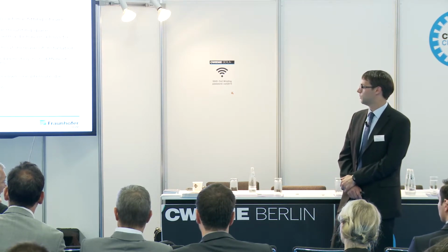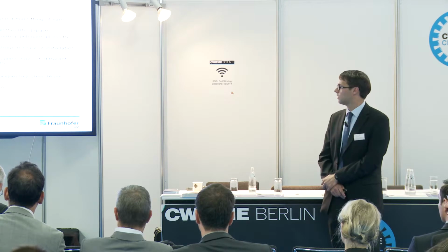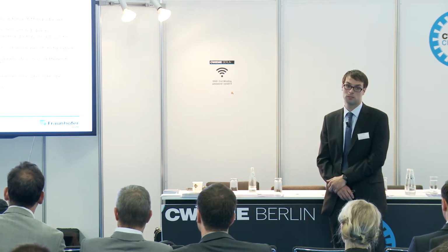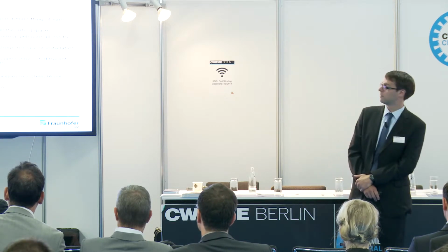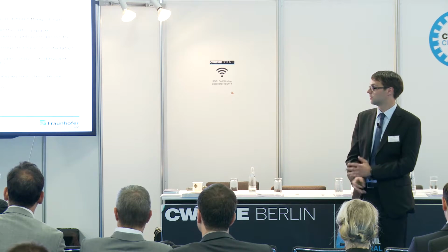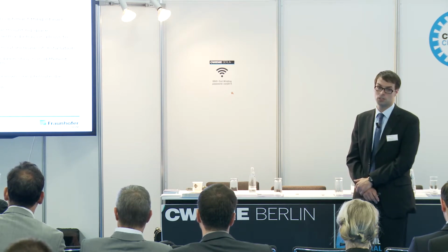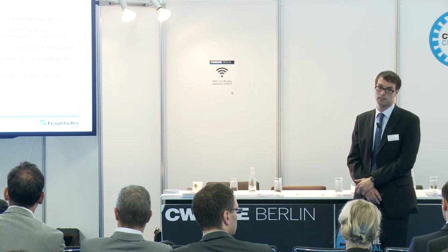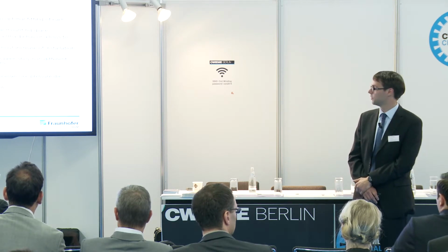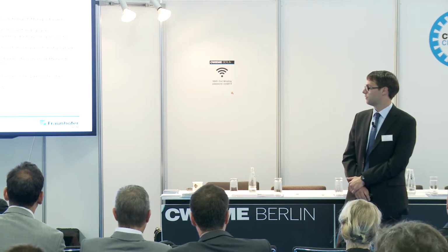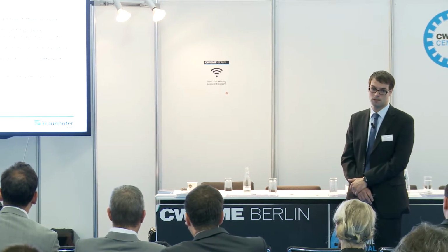In the next steps, we will do further research on the process development for highly productive casting processes. We want to produce the coils in die casting process to reduce costs and to realize really cheap coils. And we will adapt the process to distributed winding systems, to realize distributed winding systems with casting coil process, with high slot filling factor and good thermal behavior.